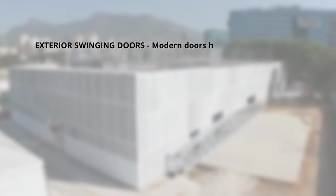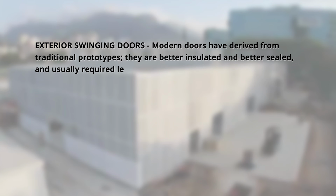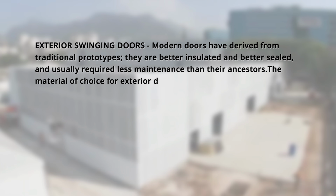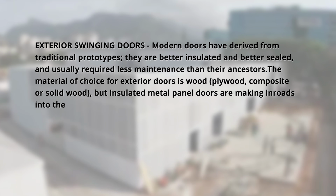Doors. Exterior swinging doors. Modern doors have derived from traditional prototypes. They are better insulated and better sealed, and usually require less maintenance than their ancestors. The material of choice for exterior doors is wood, plywood, composite, or solid wood, but insulated metal panel doors are making inroads into the market.